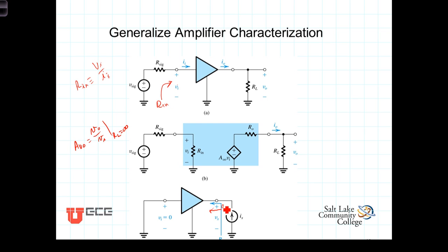So as we've seen with Thevenin equivalency, we can determine the Thevenin equivalency, at least conceptually, by deactivating the source and then applying either a voltage or current there, and then forming the output resistance Rout, or the Thevenin resistance, being the voltage that is measured, or that results when applying a current, or let's just go ahead and write it, V sub x over I sub x, or applying a voltage here and then a current flows into it.